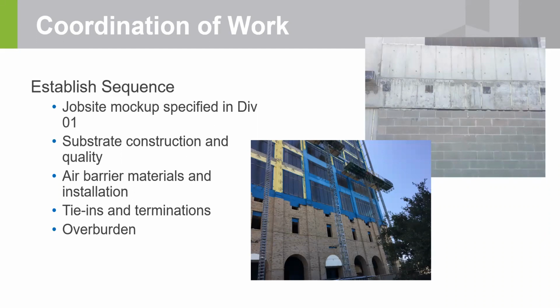You're tying into that. You're not caulking at the face brick, for example, trying to do your air barrier. Everything's got to join physically at the air barrier level. In the planning stage, you have the shop drawings where you do what's called a pencil test, where you identify the layer that's your air barrier, and you go from, let's say, the wall to the window, and you should not pick up your pencil as you trace over the primary air barrier from one component to another. So make sure everything is joined continuously.